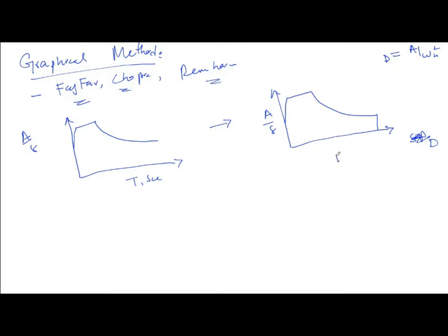Anyway, in this case the displacement may be in inches or millimeters or centimeters. Now in this case, on the x-axis there is displacement and on the y-axis there is acceleration. So it is this standard design spectrum that is converted to the ADRS. This is known as the acceleration displacement response spectrum, ADRS spectrum.